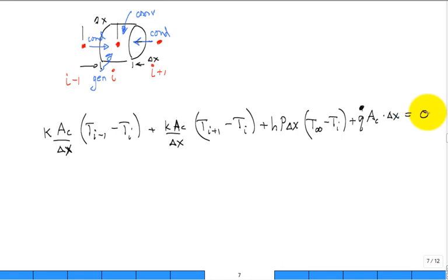When I have the true final steady state temperature distribution, that equation is satisfied. I'm looking for the unknown temperatures. So in each of these equations, I typically will have 3 unknowns in one energy balance equation. So what I'm going to get is a coupled system of equations. They're going to be linear algebraic equations. Maybe I'll get 10 equations, 10 unknowns. I'll have to solve them.